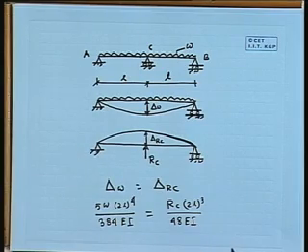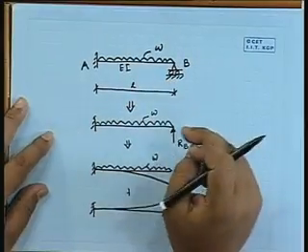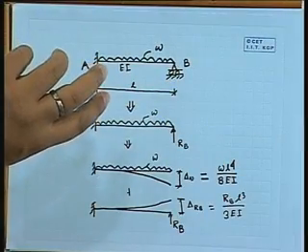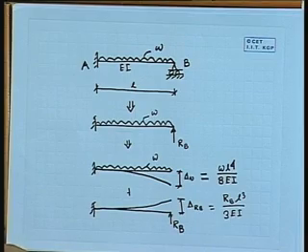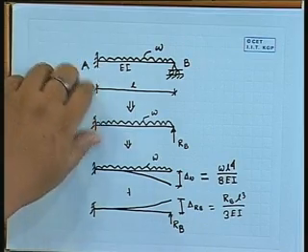Or if I take the cantilever problem, we have removed that. Here the restraint against rotation we can release. So we can make it simply supported. We can make it a hinge support with an applied load, and that load will be in the form of a bending moment. So one bending moment will be acting at the end, and that bending moment is an unknown quantity.